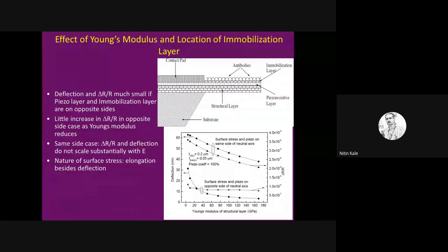Other questions: if you change the material properties, if you change the top layer, the bottom layer, what happens? If you change the location of the piezoresistive layer with respect to the structural layer, it can move up and down. What happens? If you immobilize on the bottom side, what happens? Right? So those are some of the questions.